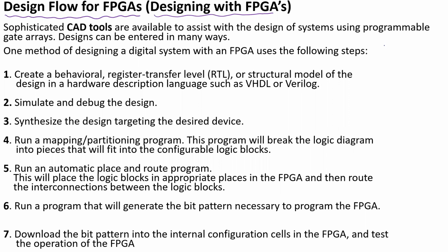As we have seen, we start with the idea. This idea has some specifications that will be implemented with HDL programming. For this HDL program, we need to verify the syntax errors and debug whatever is in the HDL description. That is called simulation.